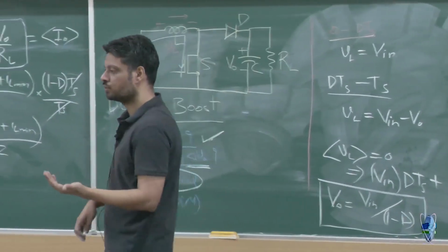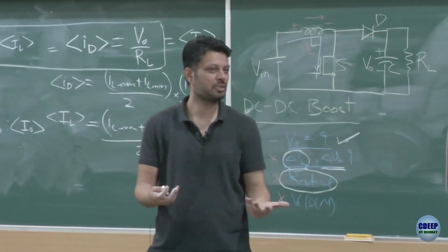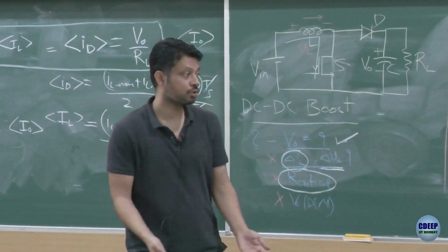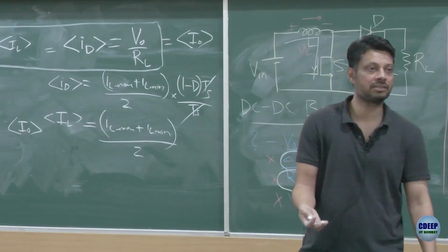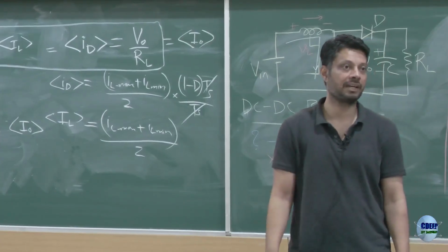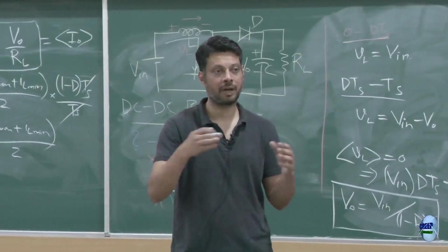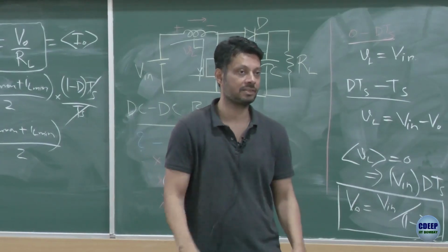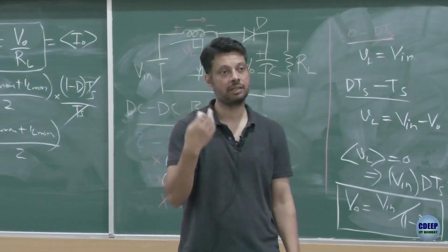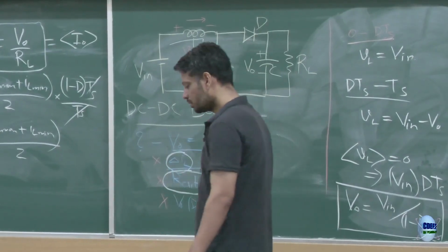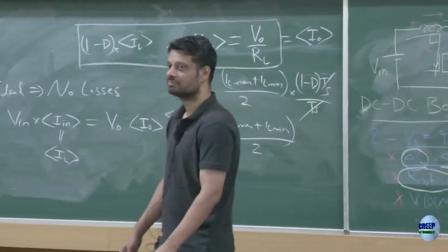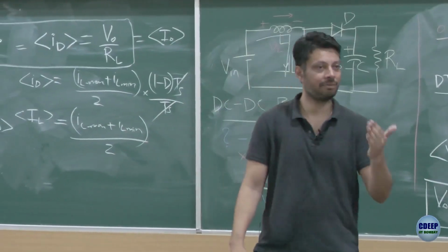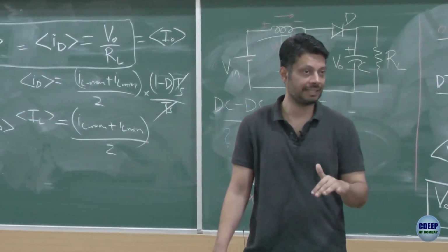What is the general frequency of switching in a boost converter? Again, it depends on the application. I have seen some boost converters operating as low as 5 kilohertz, and of course I have seen boost converters operating at megahertz. So depending on power, voltage level, and current level, different applications may have different frequencies, from 5 kilohertz to megahertz. In this basic course we don't really cover those things. At a later advanced course you can go into those details.